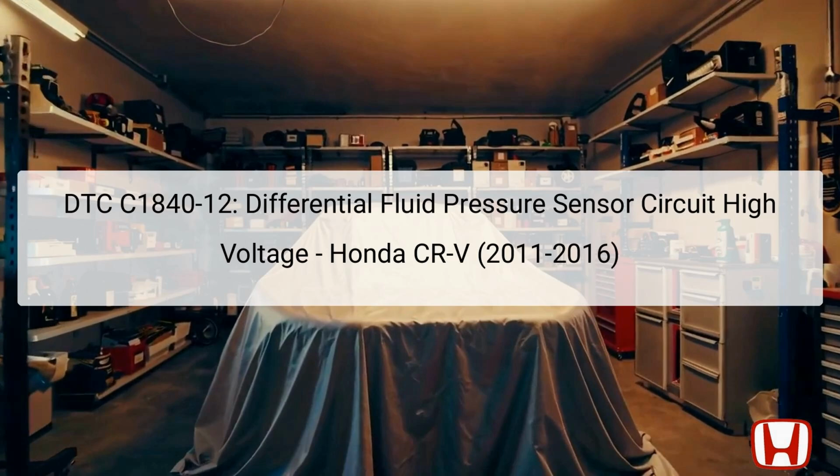The Diagnostic Trouble Code, DTC C1840-12, signifies a high-voltage issue within the differential fluid pressure sensor circuit. This code is specifically linked to the real-time all-wheel drive AWD system in the Honda CR-V models from 2011 to 2016. The differential fluid pressure sensor plays a crucial role in monitoring the oil pressure within the rear differential, which is essential for optimal operability of the AWD system.